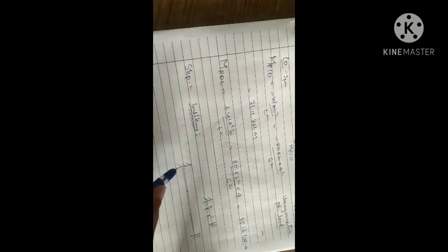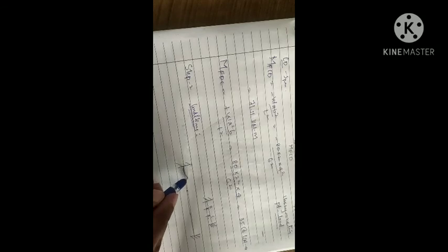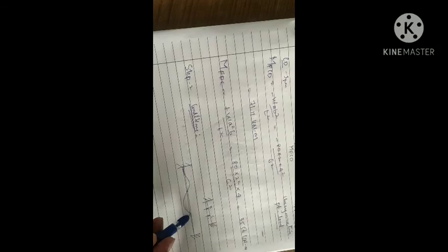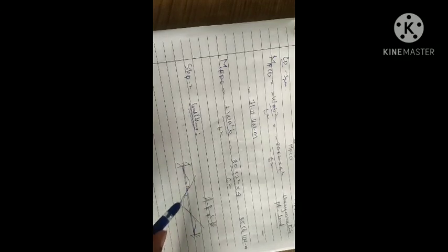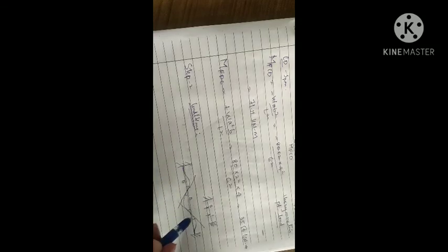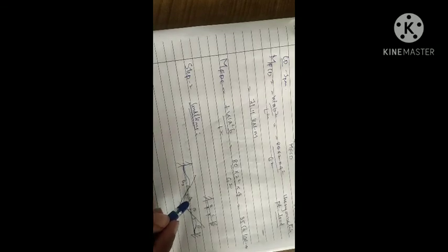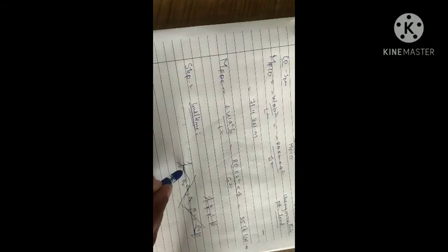If you see the deflected shape of the beam, it doesn't rotate at the fixed end; it rotates at the intermediate supports. At the fixed end it is held tightly, so there is no slope development, and the slope will be developed at B and C. Slope is the angle, so slope is theta. Here you will have theta B and theta C. Here there is no angle theta.